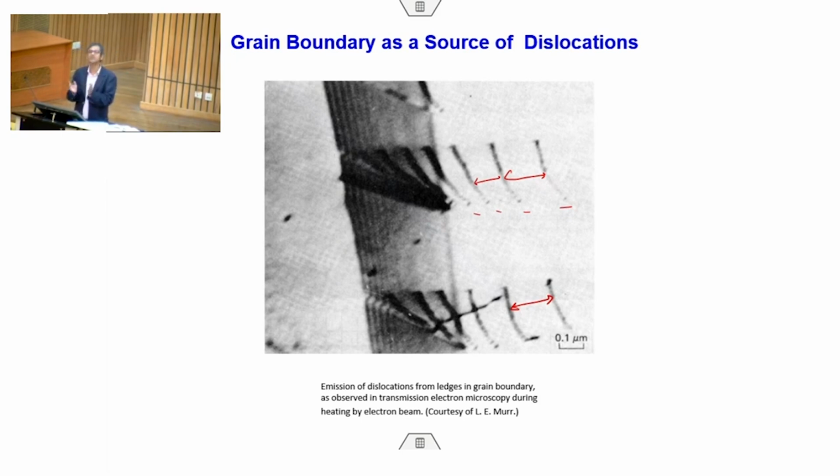If the stress fields overlap, it will lead to an increase of energy, and many things can happen. But it is not possible to have these two dislocations coming closer than a certain distance. In fact, the distance can also be calculated knowing the stress field, the Burgers vector and many other things.